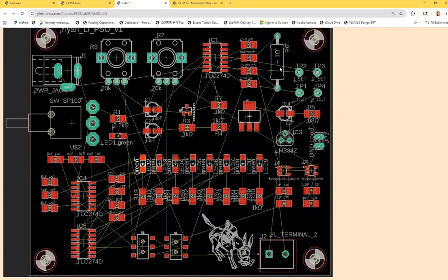So that's a special resistor, 1 ohm. It's a power resistor. It's just so different from other ones. It's for high power, running a lot of current, so that's why it's huge. But for all the other components, like I told you guys, the footprint of the parts could be some standard packages used for that component. Since you already did the first schematic, what's a very typical or standard package we are using for the resistors and capacitors in here?